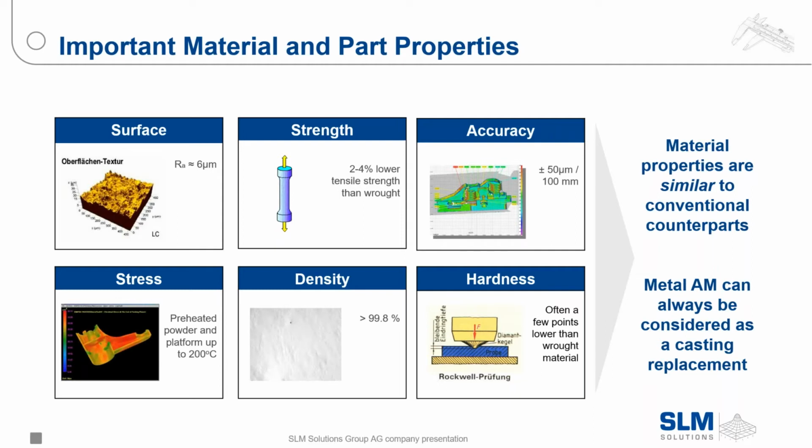This is a close-up picture of the microstructure of the material as printed. You can see all the waves throughout this. These are layers upon layers of weld bead laid down to produce the part. You can also see the borders and the fill contours inside there, and right there on the side, you can see some porosity. The SLM process says it's 99.9 to 99.98% dense, so there's always the chance of some porosity, and this has to be taken into consideration.